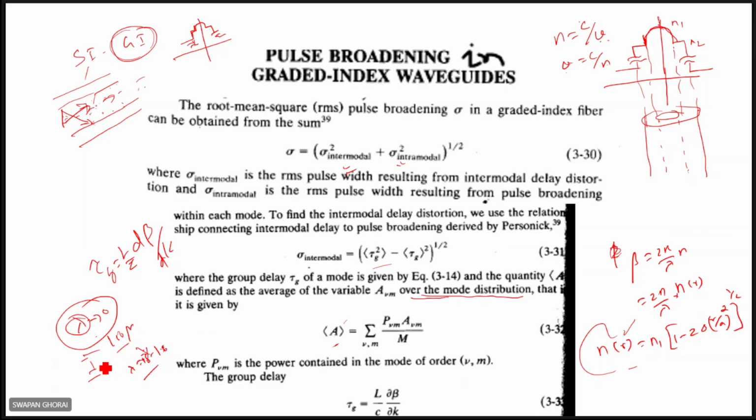So in multimode fiber, you can use ray optics, but for single mode fiber you cannot, because the core diameter can be 2 to 10 microns. Suppose the core diameter is 2 microns and lambda is say 1 micron or 0.8 microns. With respect to 2, we cannot neglect 0.8. So it is comparable. That's why ray optics fails to explain the propagation of light in single mode fiber. At that time we have to consider mode optics.